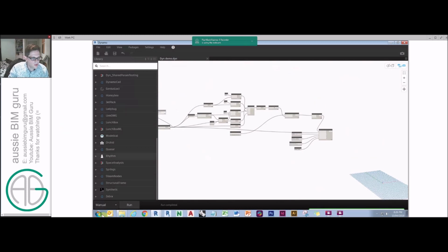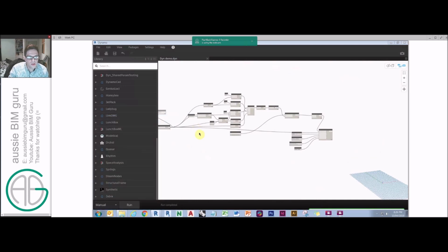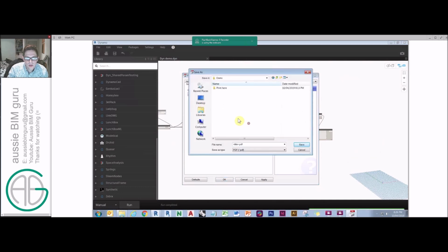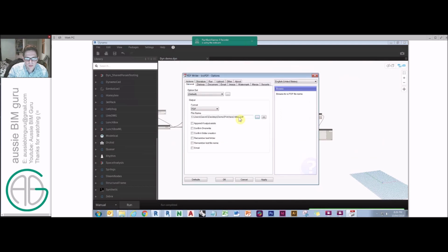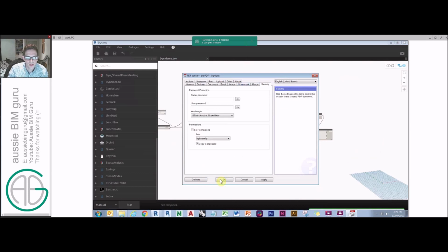But what we need to do first is actually visit some of our settings instead. So a lot of plotters will typically have settings that you need to customize. So in this case, I've taken an area and said this is where I want my documents to go to. So I'm just going to say that my documents are going here. And there'll be a little bit of hoop jumping that you'll see in the way the documents are named, which we'll process after. And I've turned off everything that basically confirms things or gives me dialogues. So I just say I never want to see save as, I never want to see my settings, I want all errors to be suppressed. That way it just goes straight through to print. You don't get any dialogues trying to get you to put in certain settings as you go.